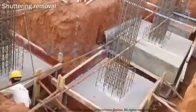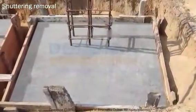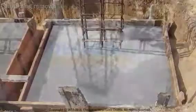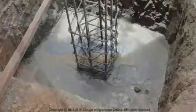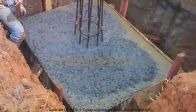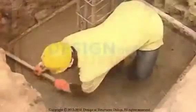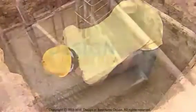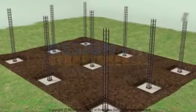Shuttering removal. The formwork removal procedure should be supervised by the engineer to ensure that the quality of hardened concrete and structural member is free from, or has minimum, casting defects such as honeycombing, size and shape defects, etc. These defects in concrete influence the strength and stability of the structure, thus immediate repair works can be done or the members can be rejected.